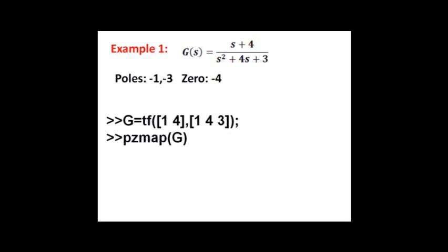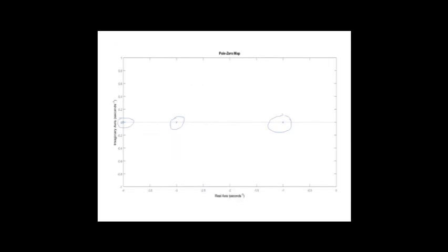Enter the two coefficients using tf and assign it to our source variable Z. And in the next command line, call pzmap where the input argument is Z. Your successful execution should show you the return as you see on the screen. Poles are indicated by cross marks and zeros are indicated by dot marks. We have shown poles and zeros using encircled lines on the displayed graph.